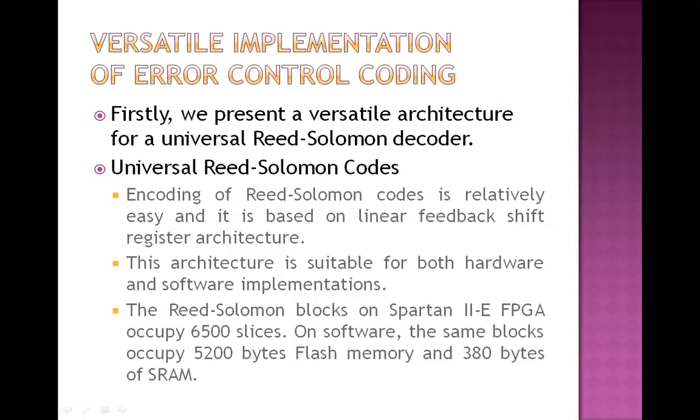In recent years, a new powerful coding scheme is emerging due to its error correction capability. The low density parity check codes outperform many block schemes, and for a long length they approach the Shannon limit. We analyze the potential of this code within sensor network application and present the ASIC realization.